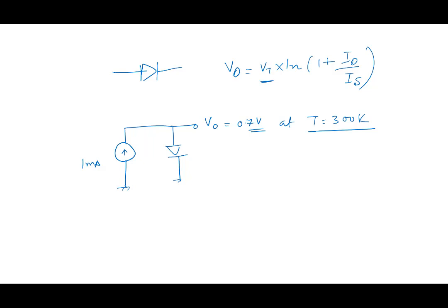Diode voltage is temperature dependent. Right? Now I change temperature. So this is 300K is 27 degrees Celsius. Go to temperature equal to, for example, the diode could be used in an ignition of a car somewhere, where the temperatures may rise up to 100. So let's say T equal to 100 degrees Celsius. 100 degrees Celsius you add here, you'll get what? 373, right? 373.